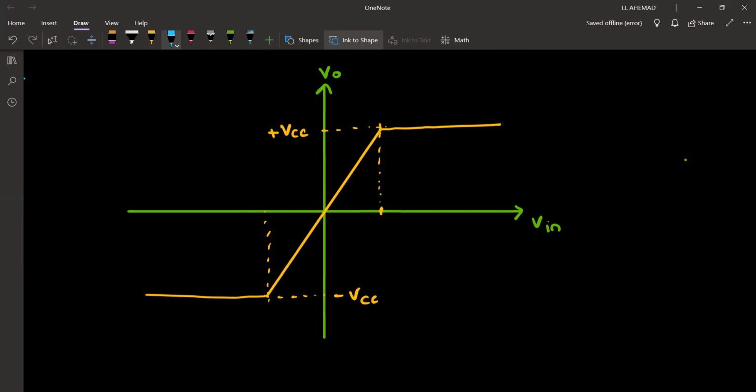So here, this gap, if you check for this gap, it is around 150 microvolts. So if my input is 0.1 volt, then what can you tell about this amplifier? Will it amplify or get saturated?